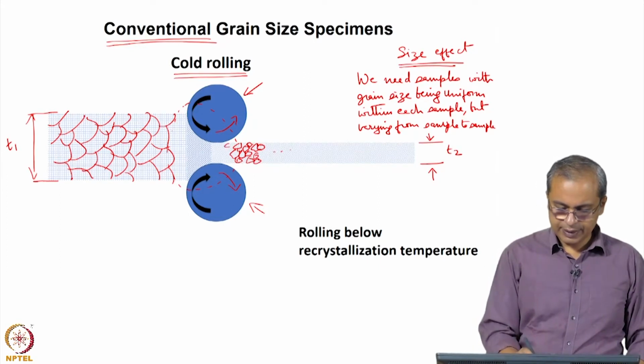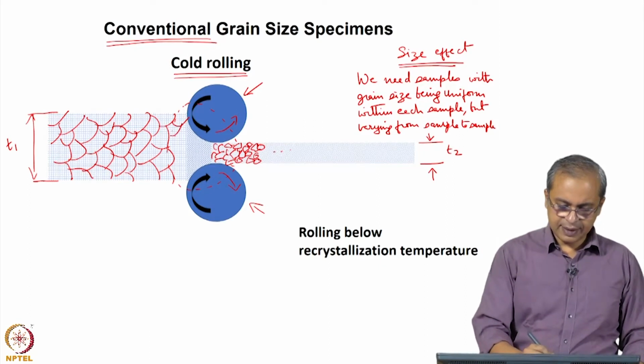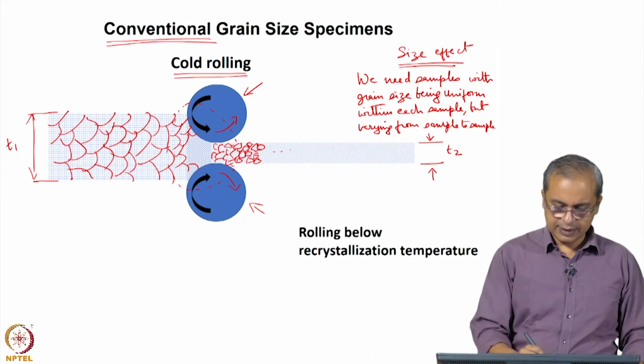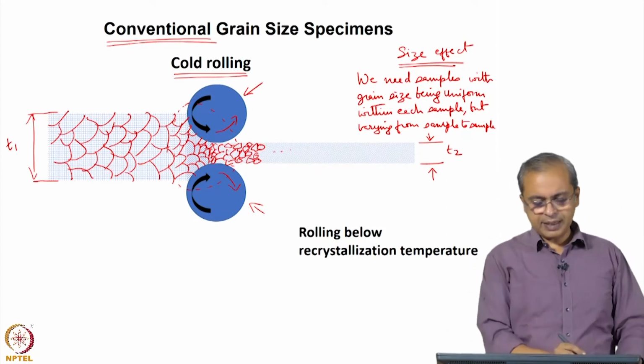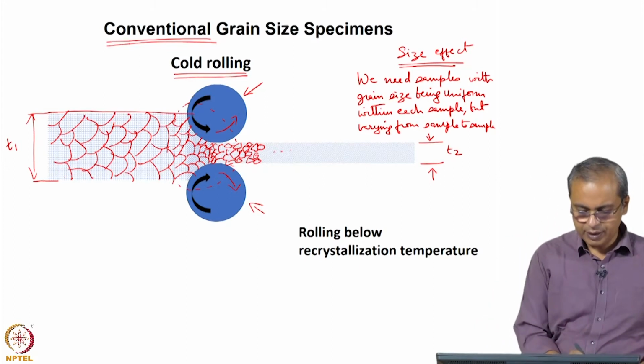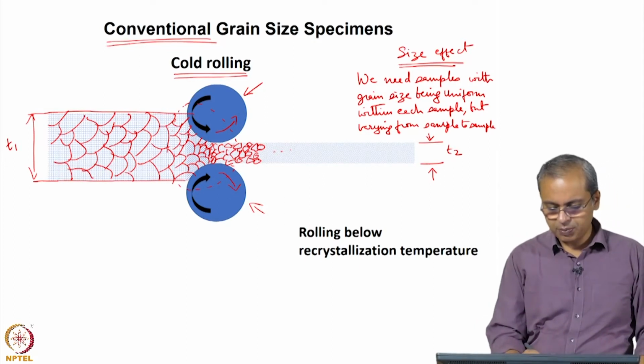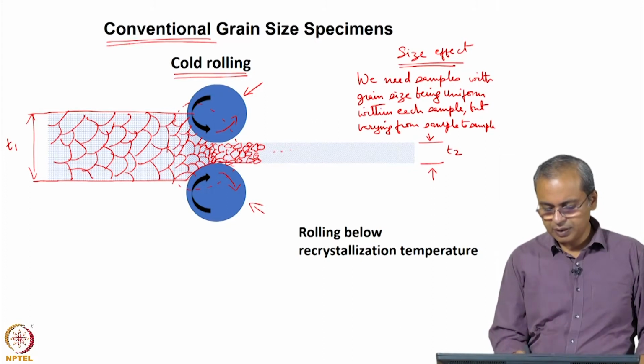So, that continues in that direction. And in the transition region, slowly it goes from larger grain size to smaller grain size. So, that is basically what you start seeing. You see something that starts off as a large grain size material out here, and then as it gets squeezed, it slowly becomes a small grain sized material and comes out this way.